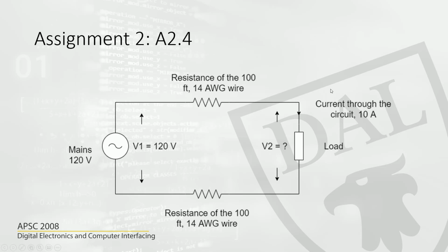So this is an important calculation again. When you're buying an extension cable, and if you know how much current you will be drawing, make sure you take this into consideration. Usually these things will be mentioned on the extension cable. So what is the maximum current you can draw from the circuit? Based on that,